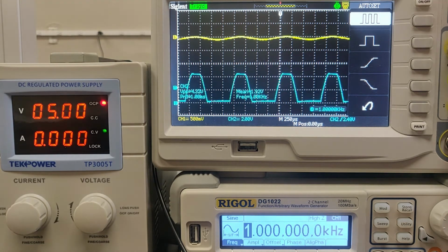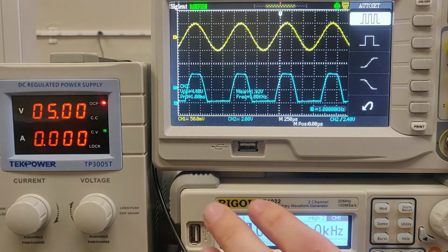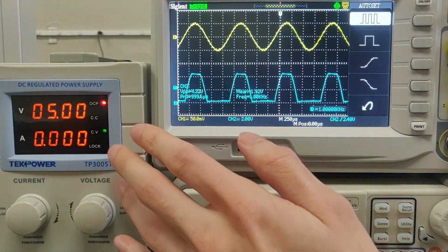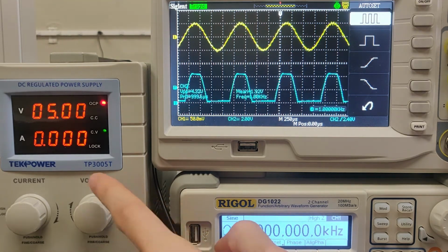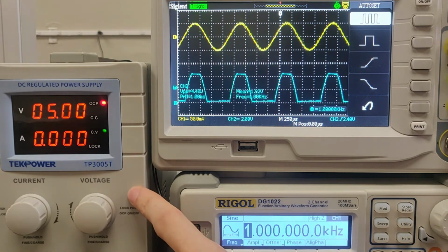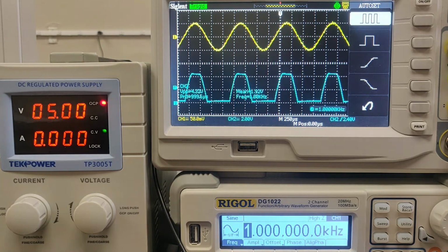So right now, it doesn't specify what to set our power supply to, so I just set it to 5 volts, because that's kind of been where we've started in the last two parts. But we can see that given this window of 5 volts, our amplified signal is clipped, so it's not being fully displayed.